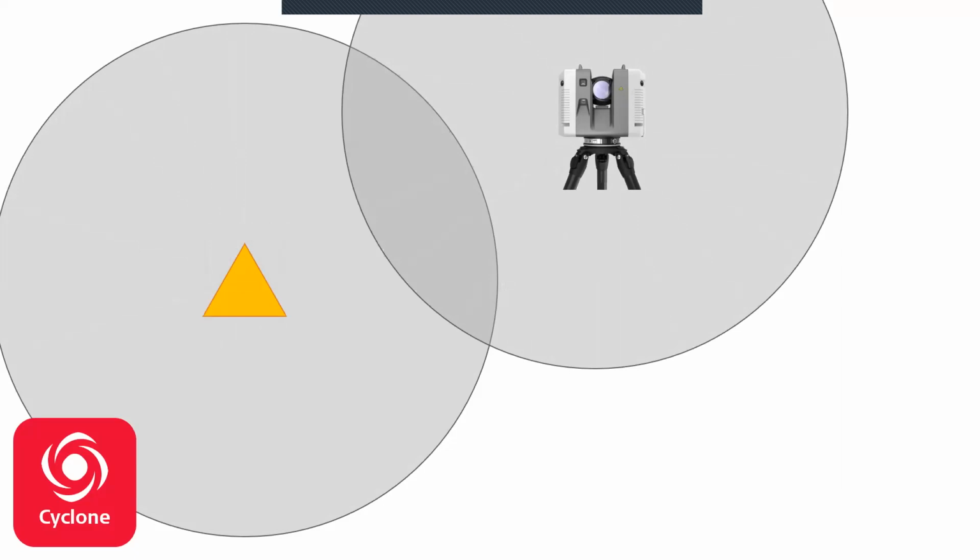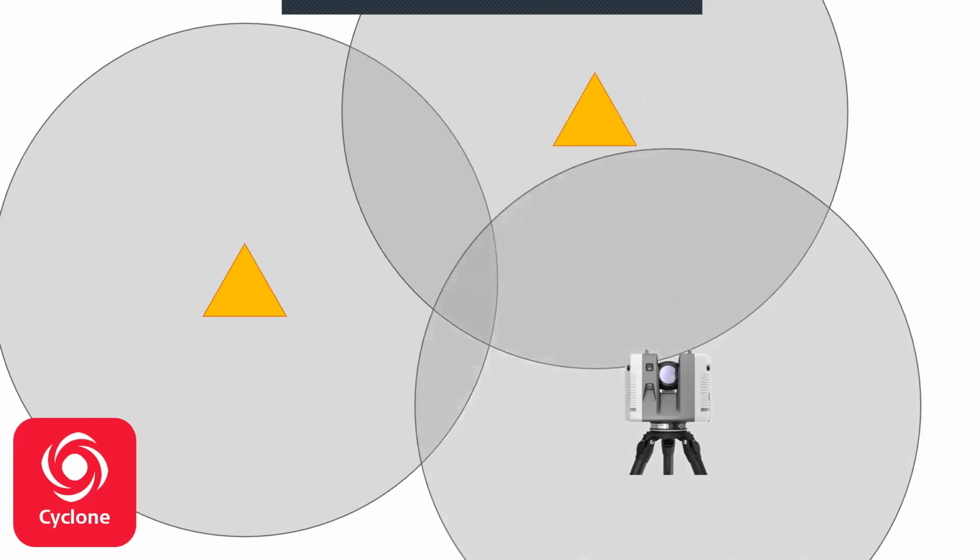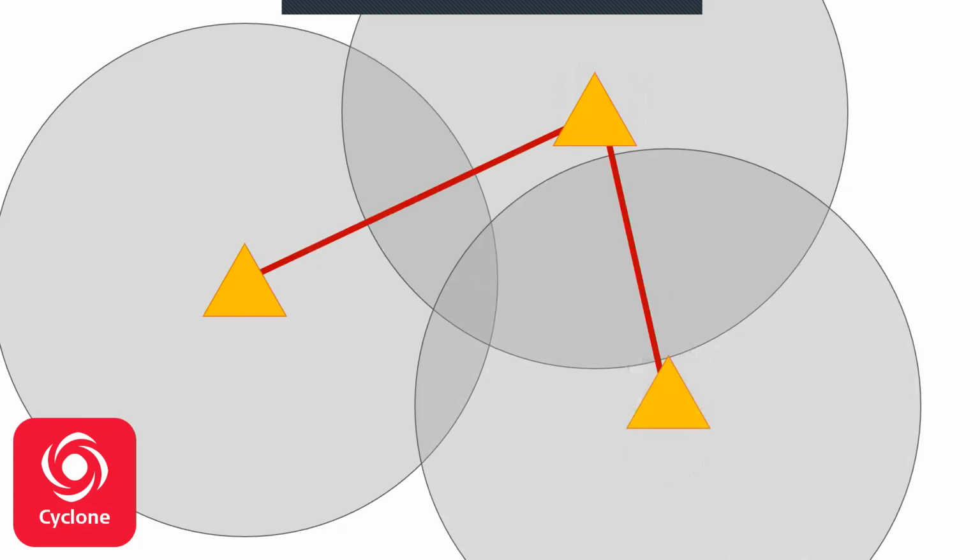The same thing applies when you have a home with 5 rooms or 6 rooms or 2 rooms. When we want to make a complete virtual 3D model of it, we have to go into every room and take one image. In the same way, when you want to measure buildings and have the full structure all around, you need all those structures together. We take multiple scans around the area with some common areas so that we can understand the dimensions. The software, Cyclone, allows us to create the connection between all these scans together, whether 5, 10, 100, or even 2000, 5000 scans.